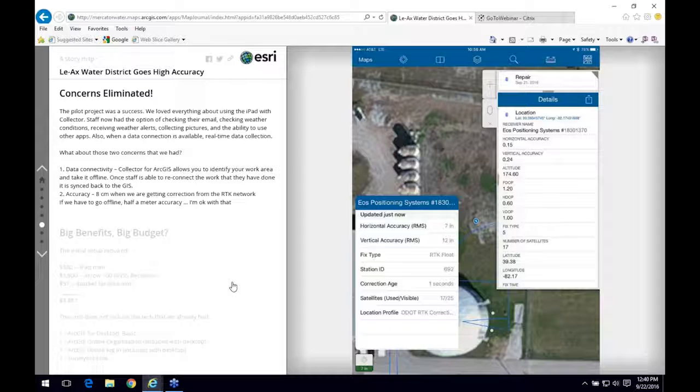And if it's a leak, or if you're going out there to mark a line for a spot dig, the hoe operator is going to rake across that point, a 4-foot swath. He's going to look for that ditch. So if we had a GPS point and it's within half a meter, we're going to find that water line really quick. So it's like the operator says, get me within a bucket width, right? Get me within a bucket.